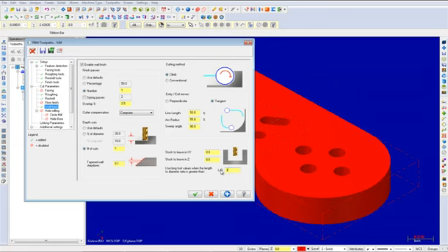The rest of your parameters should appear as shown. I will now explain a few of these parameters. Finish passes defines how many passes the tool will step down the part. Number lets you enter the number of wall finish passes. Depth cuts defines how Mastercam divides the total depth cuts for the FBM generated toolpath type into multiple depth cuts. Number of cuts enters the number of passes you want Mastercam to create in the FBM generated toolpath. And finally, entry-exit moves will define the tool moves Mastercam uses when entering or exiting the finish cut pass.